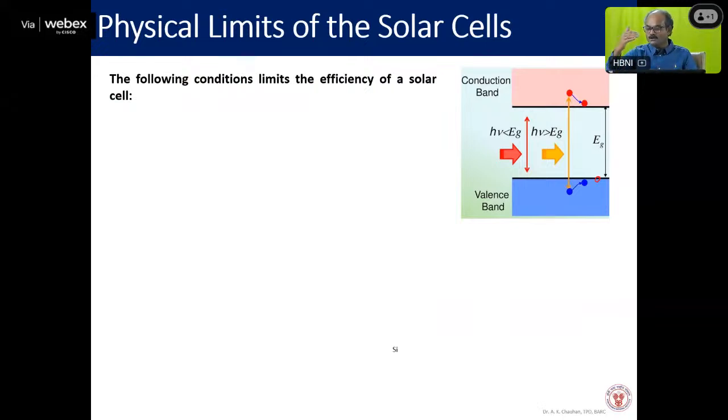If you reduce it a little bit because of the impurity level, consider 1.1. So my band gap is 1.1 only. And I have the entire spectrum of the sun, which I saw. Just recall the solar spectrum of the second slide. So that entire spectrum is coming.